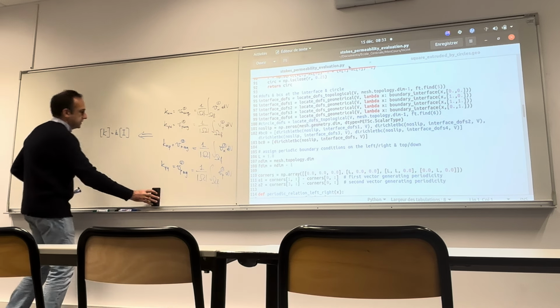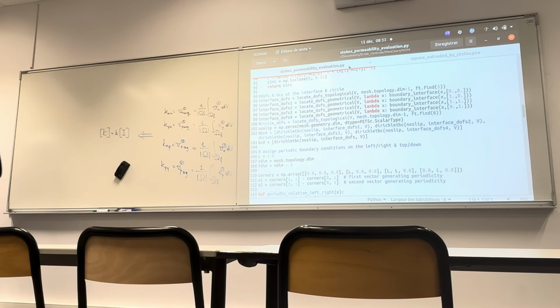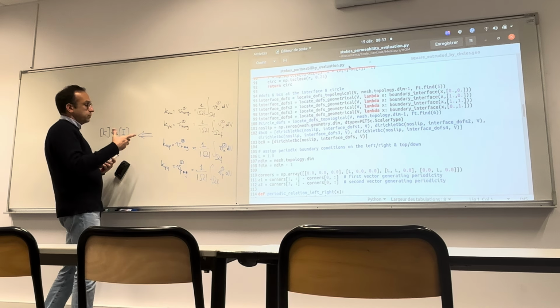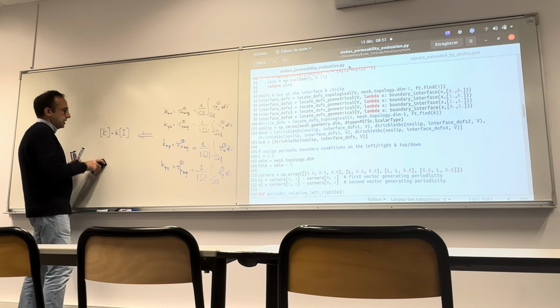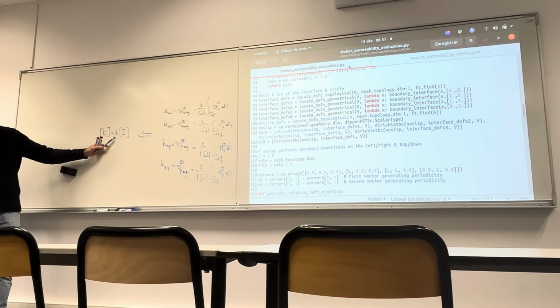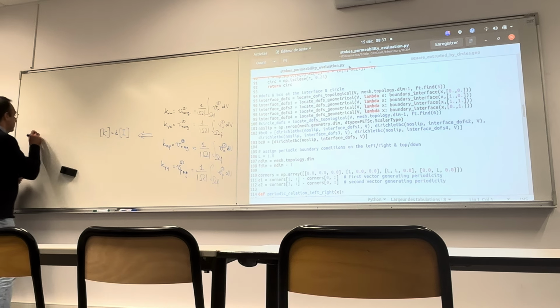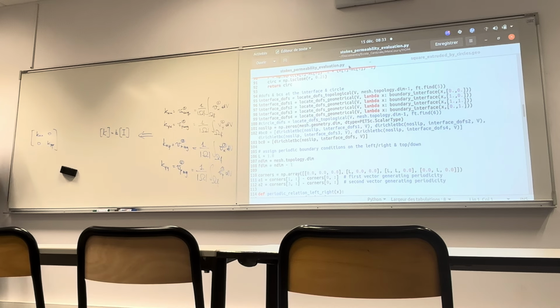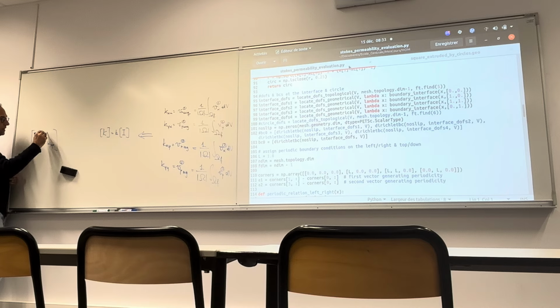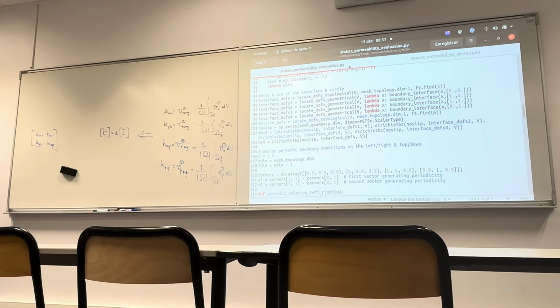And so the point is that by changing the position of the circle and modifying its radius, you will observe a certain number of conditions in which, first of all, you can obtain, rather than a spherical tensor, so just a permeability, a situation like this, with KXX and KYY different from one another but still a diagonal matrix, or even the completely anisotropic case, obviously still symmetric, where these two should be equal but different from 0.